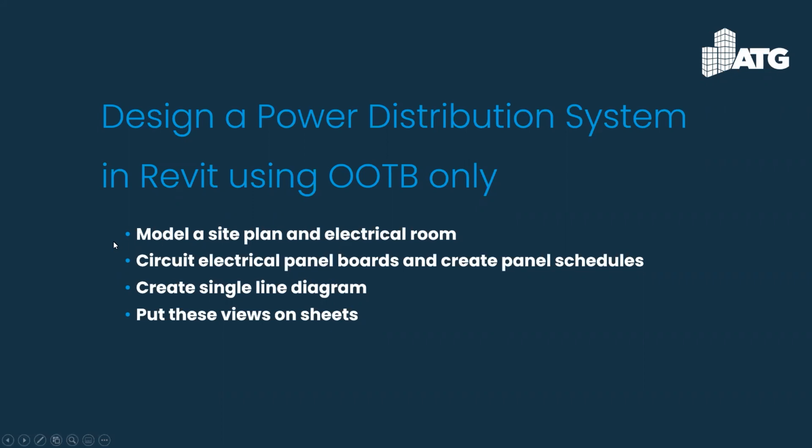Today, we're going to model a site plan, an actual electrical room. We're going to circuit some panel boards and create some panel schedules. We're going to do a single line diagram, and we're going to try to put these on some sheets. We'll see how far we can get in an hour.